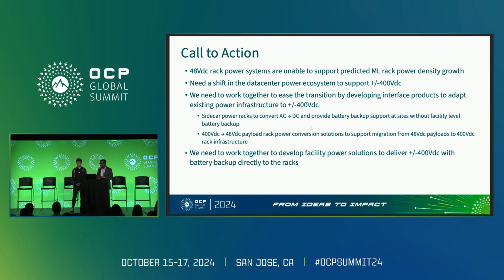But then we also need to figure out what the power distribution after that looks like in terms of the bus ducts and the fuses. Do we need circuit breakers, or can we just get away with DC fuses to protect DC for large buses? So there's a bit of development involved there. But I think up until the SSTs, that infrastructure already exists, and what we need to focus on is SSTs and beyond. And just to add to that, one more point I'd like to quickly pitch in is yes, we're talking about plus or minus 400 volt DC, great.